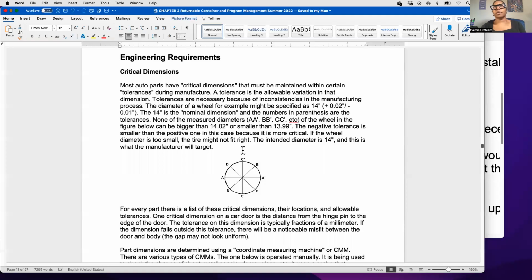So sometimes you will hear packaging suppliers asking for math data. They're looking for the 3-dimensional files that will show what the part is. It'll show the dimensions. They may have software that can simulate what the pack would look like with the part in it and simulate what that clearance is. So it's not foolproof, but it can eliminate one of the steps of prototyping.